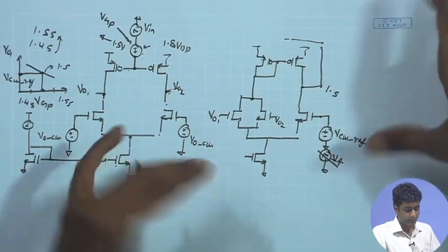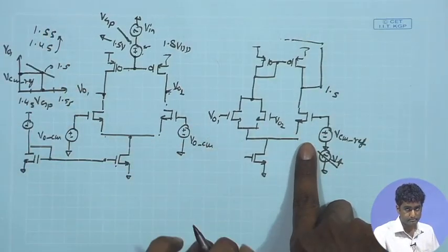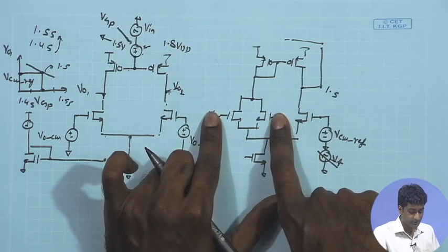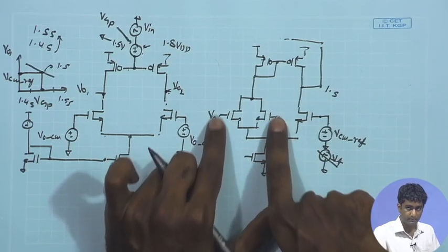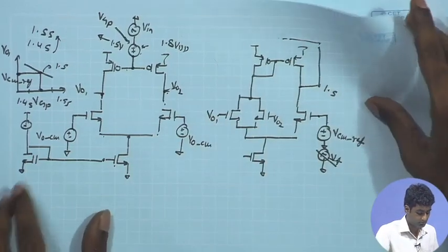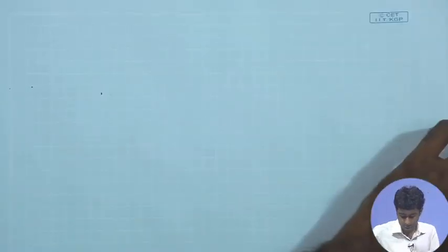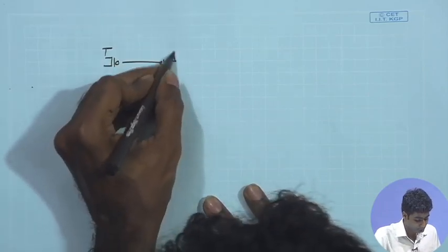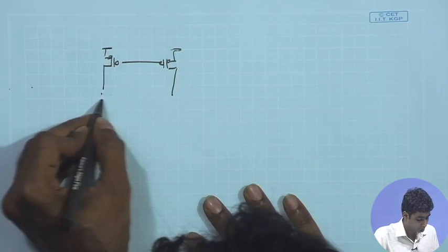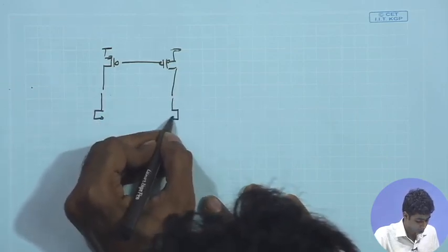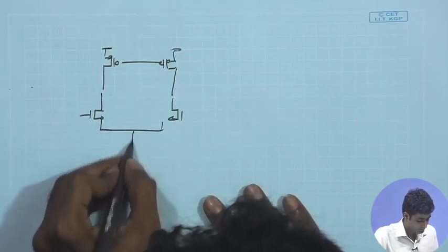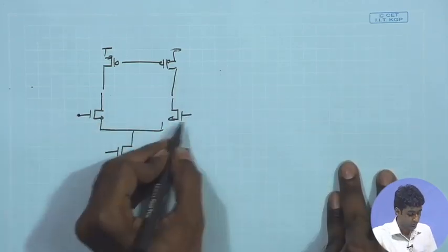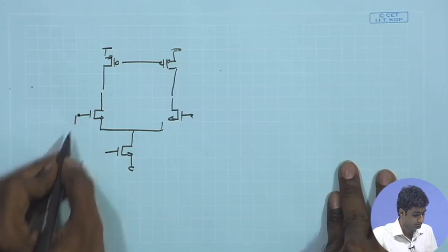Some of you have tried the other way, in which the loop can be opened, say, at this point. So, once again similar considerations. If I am opening the loop at the input point, there also we just need to make sure that the overall DC condition is maintained. Under this condition we know that once again the input points are supposed to be at the common mode DC level.